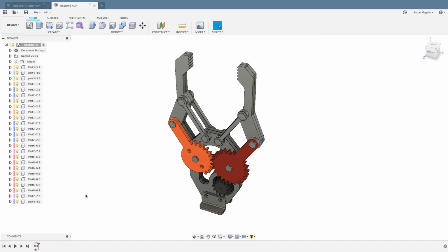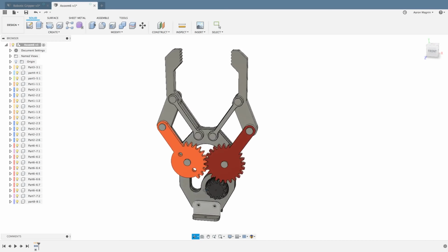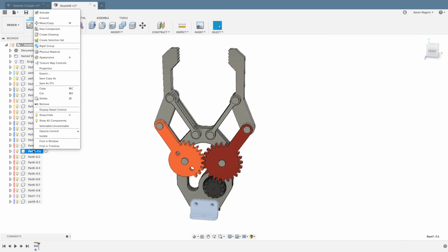So let's go ahead and let's start to design this. I do have a SOLIDWORKS background, and the first thing that you do in something like this, if you were designing in SOLIDWORKS or assembling something in SOLIDWORKS, is you'd fix one component, right? You'd want to tie down some sort of base component just to build the rest off of. And this is actually something that I think people try to do in Fusion 360, and they use this ground option to try to do it.